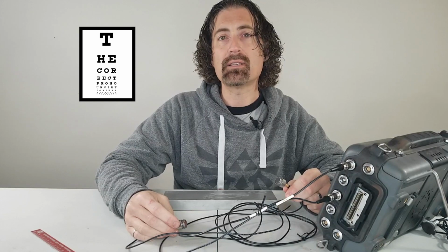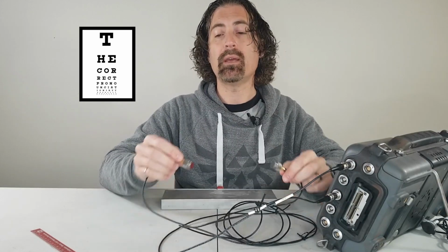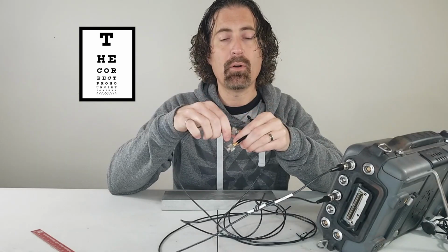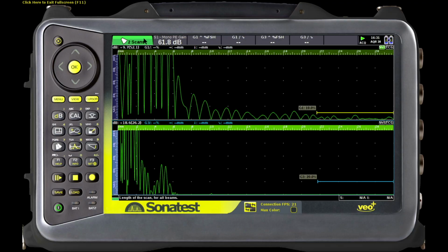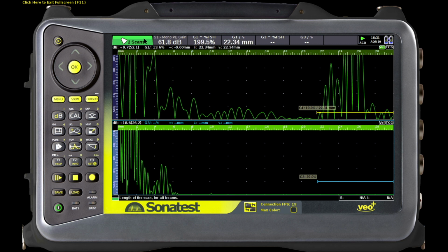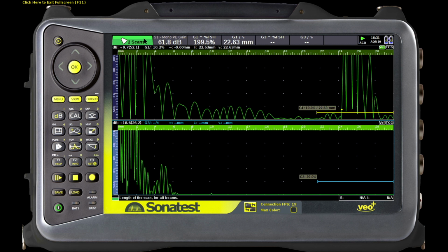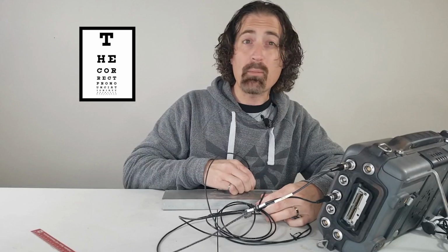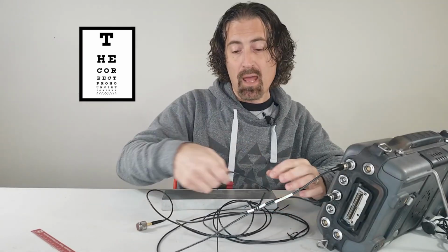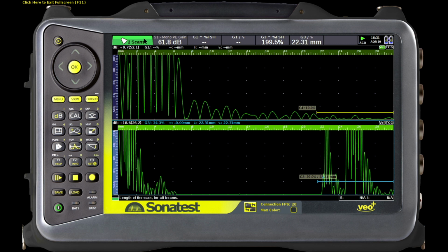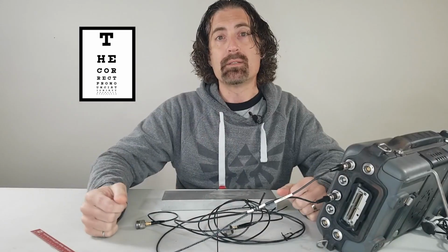Now in ultrasound, as frequency goes up, so does resolution, and we can demonstrate that. This is a 2¼ meg probe and a 5 meg probe. So on the top of the screen, you'll see the 2¼ and you can see there's the top of a square notch. So I'm just looking at the top reflective surface, blends right into the back wall signal. So it would not be fair for me to say I can resolve that. But with the 5 meg probe, it's not a problem. Again, not surprising. As frequency goes up, so does resolution.